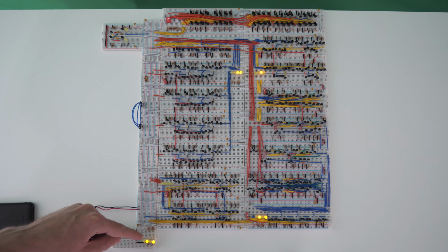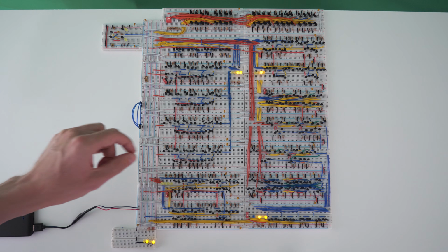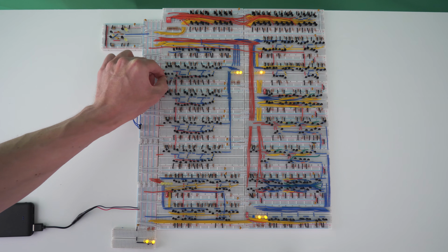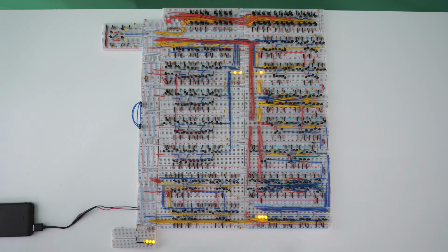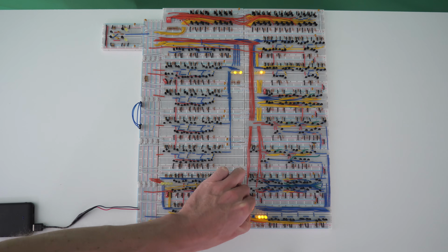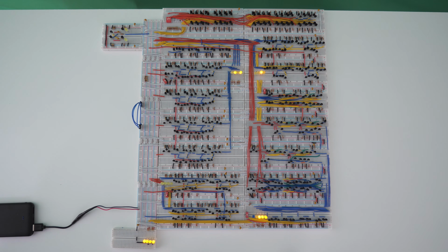And now this value of 5 that's on the data bus needs to be loaded into the A register. So we will flip this switch very quickly. And now we have a value of 5 in our A register. So we will turn off our tri-state buffers from being sent to the data bus. And now our second add command is complete.